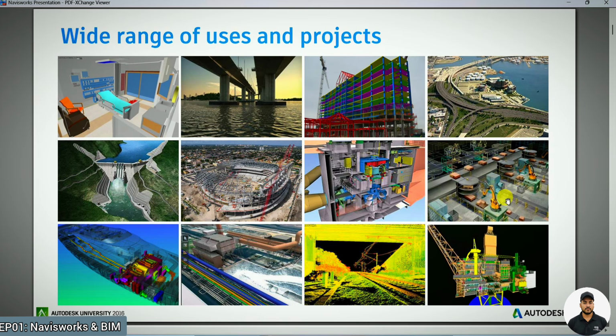Now after that 3D model, we have different subcontractors. Let's say for the MEP we have different subcontractors who prepare different models for the mechanical HVAC, for the plumbing, for the firefighting, for the chilled water, for the electricals. Then we have another contractor who has prepared the model for the architecture. Then we have a subcontractor for the facade glazing. Then we have one for the structure. So likewise we have different disciplines, Revit models, or whatever 3D software they are using to create their 3D model.